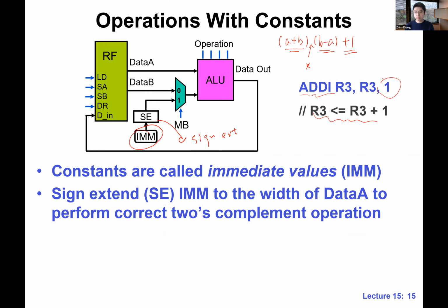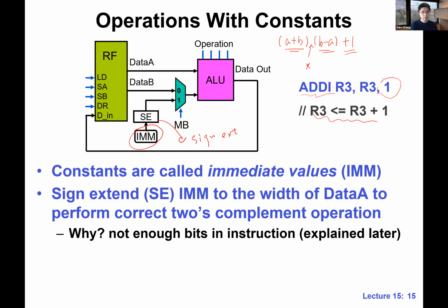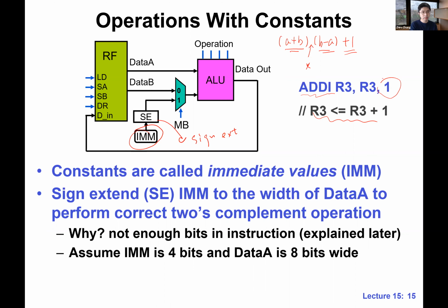We actually talked about this in one of the earlier lectures, I think last week, when we talked about binary arithmetic. When we have to add up operands with different bit widths, one of the operands needs to be sign extended in the 2's complement format. So assume for now that all of these are stored in 2C format. Because usually we can only store short, small constants in the instruction. This is going to be very clear in the next lecture. That's where we need a sign extension.